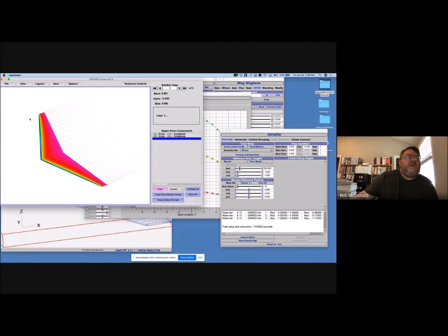And for a lot of inviscid aerodynamics, so for things like trimming the airplane, for the lift distribution, for the primary structural loads, for all of these things, the thickness distribution of the airfoil doesn't matter that much, right? So now I know Mark Page is really into designing airfoils, and he's very good at it, and he often designs some laminar flow airfoils that are very, very careful about their thickness distribution. But Mark, I think, would totally agree with me in that when you're doing this analysis, it's an inviscid analysis, meaning no friction. And so that very nuanced thickness distribution in the airfoil that Mark Page has designed doesn't matter for this analysis.